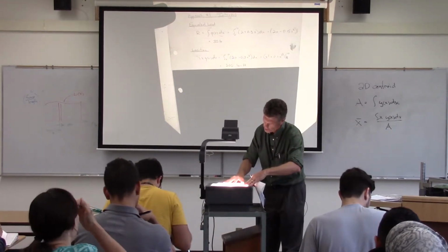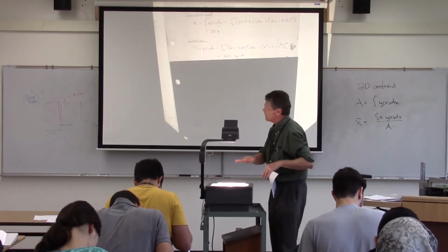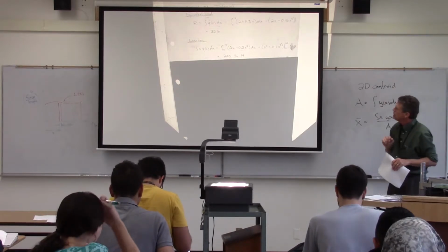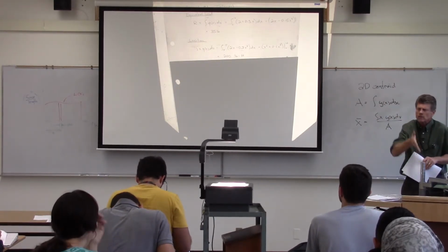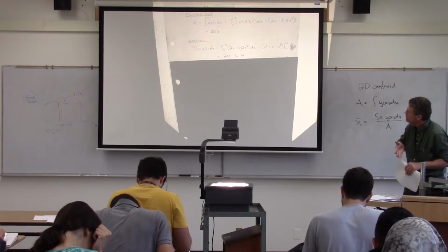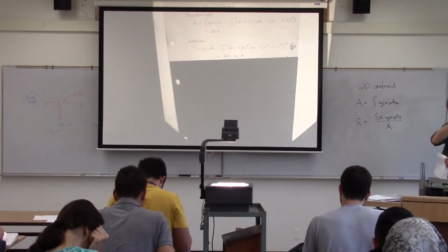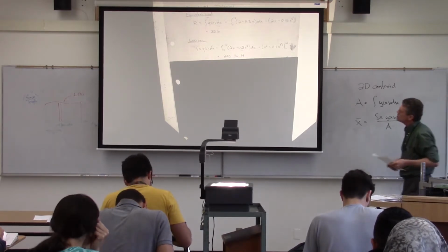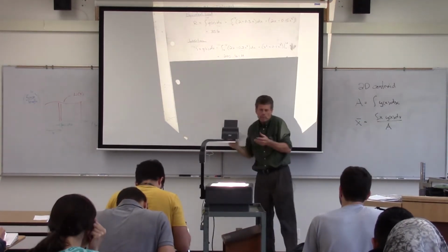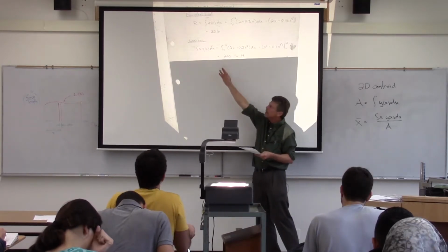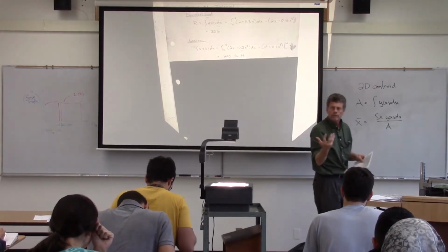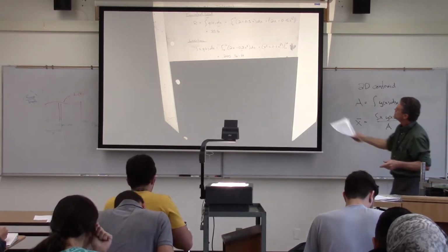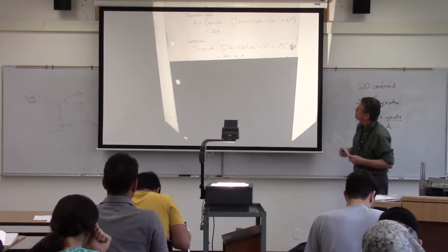is finding that location. Basically, that's the first moment of area again. Now, it'll be about the y-axis, but that's fine, because I'm only interested in x. I've got this load acting vertically down. I don't really care about y because there's nothing horizontal going on there. But I need to find the x direction, and it's simply going to be x, since I'm taking vertical strips: x_c equals x multiplied by that linear function q(x), taken to the limits of integration.